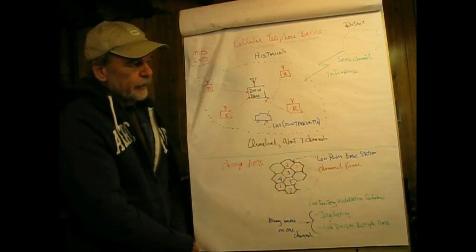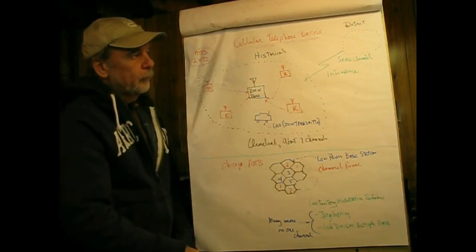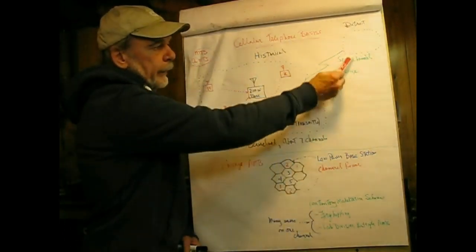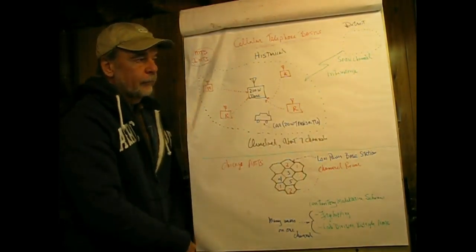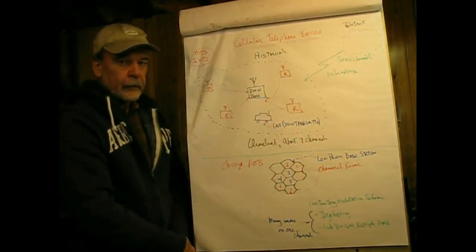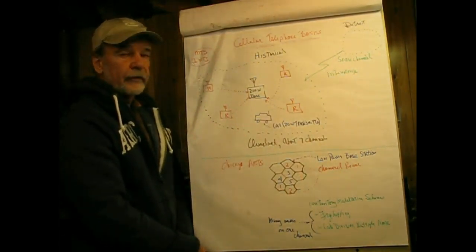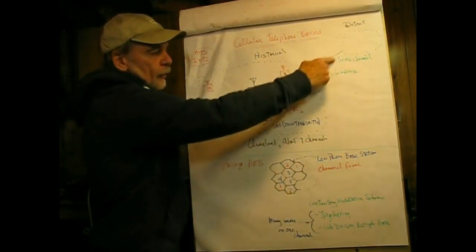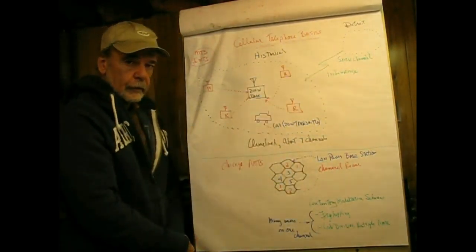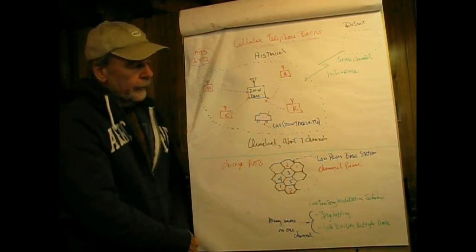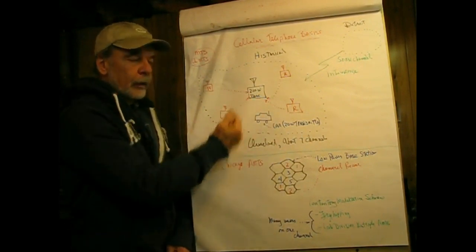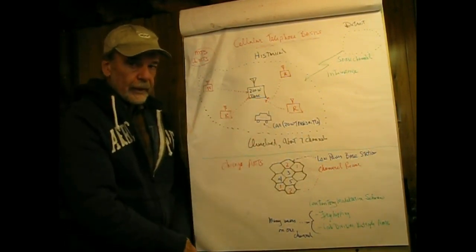So channel reuse was an issue. Here's Detroit, and they had one channel allocated on the same frequency. And in the early mornings, there was absolutely no difficulty for that Detroit signal to ingress into the Cleveland signal. So the issue is when you're dealing with 200 watts, it goes a long way.